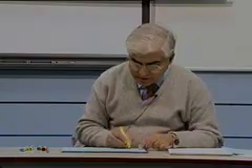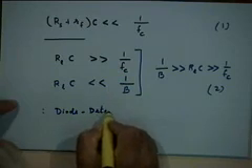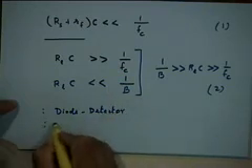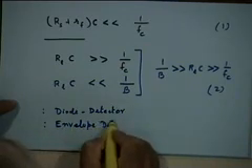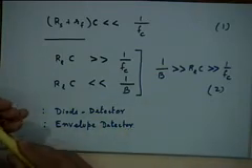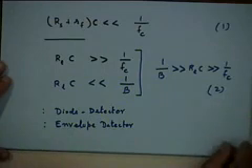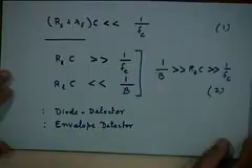So this is what we call the diode detector. It has various names. We also call it the envelope detector. And as you can see, just with these three components, a diode, a resistance of a sufficiently large value, and a capacitance, you can build a very simple demodulator, right? And that's what most of your AM receivers do, that you use in your homes or whatever.